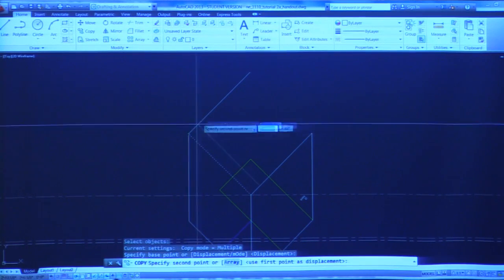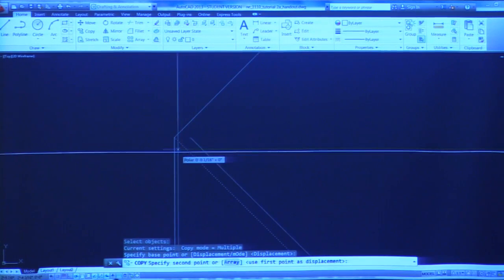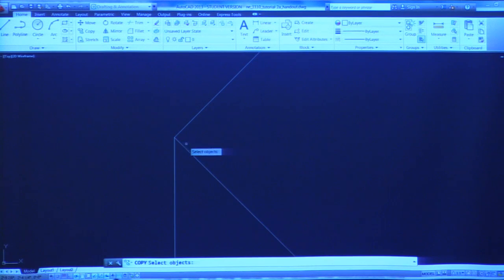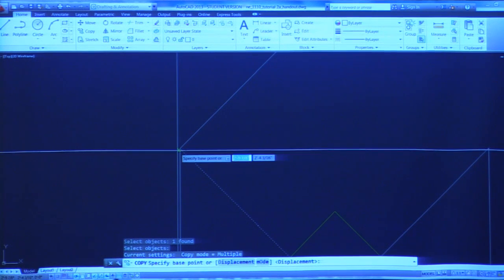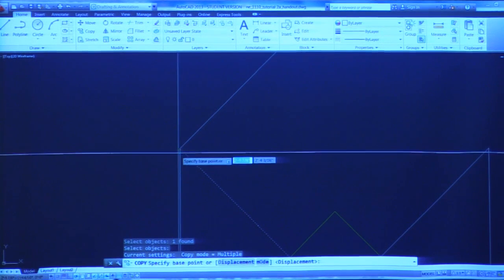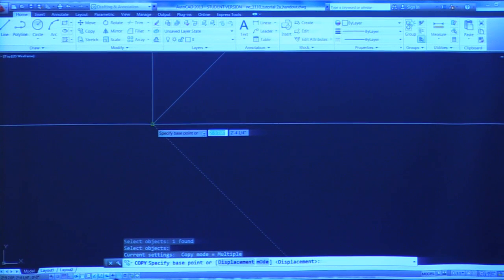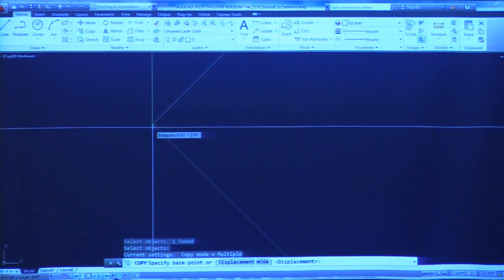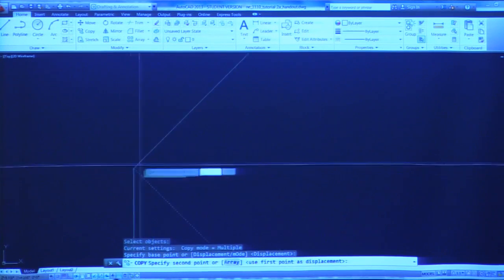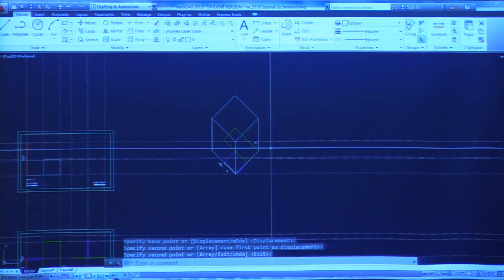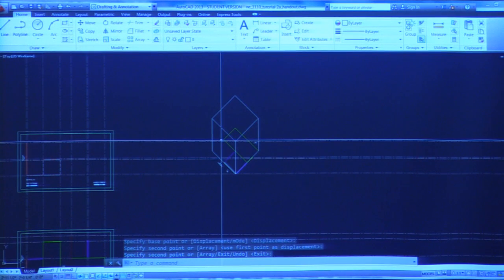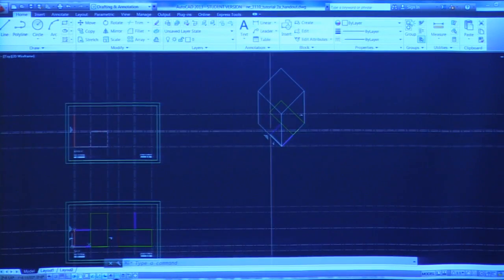See, I'm redoing that because when I select my line and go to copy, you see that little right angle sign, that little green guy? That's picking a perpendicular point to that line. I don't want to do that. I actually want to pick an end point. So you see the difference between the different snaps as they go up? You'll get used to that, but you want the green box because that means an end point. So this is my imaginary box that I'm drafting my cube in.